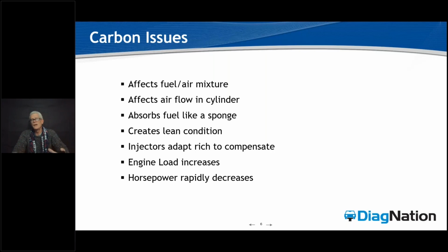Meaning we know as soon as we throw carbon into the mix, and move or upset the tumble and swirl of that charging of air into that GDI cylinder, we're going to start to affect airflow, air and fuel mixture, and burn characteristics in that cylinder real time.